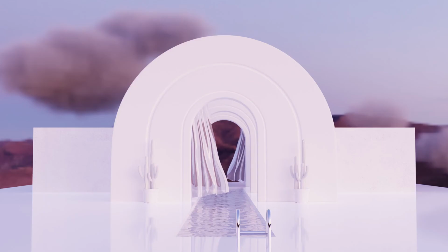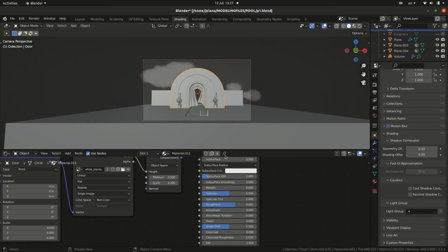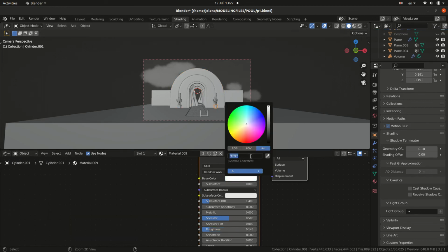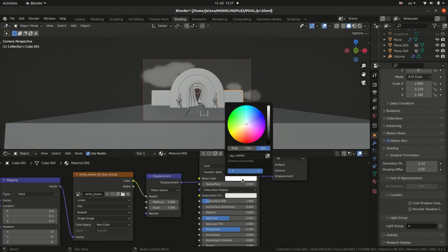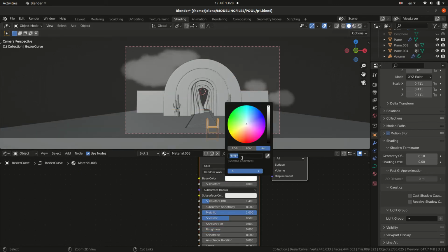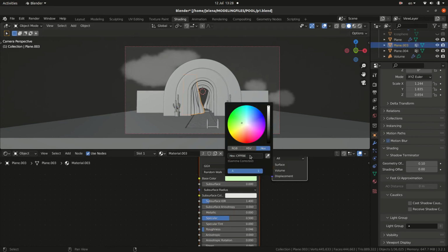And let's change that color and see the same effects. So pick any color you want, and remember this color depends on your lighting, HDRI this time, and your camera angle, not only texture. So pick any color you want and just change it and see your results.